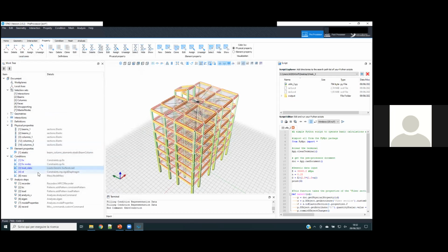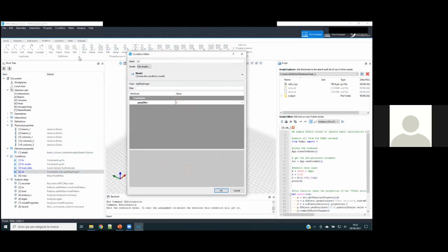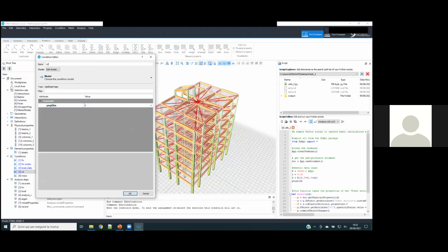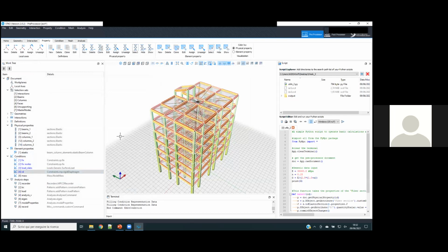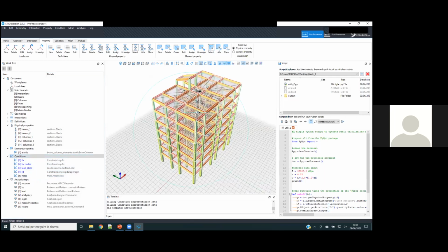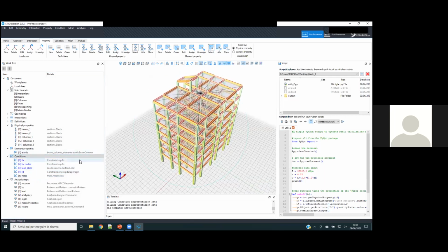So great. Another thing that I have to put in my condition is a rigid diaphragm in the third direction applied to the interactions that I created before. And as I repeat all the time, mass and load are not the same concept in OpenSees and STKO. They're not automatically transposed one into the other. There's nothing inside that will do that for you.